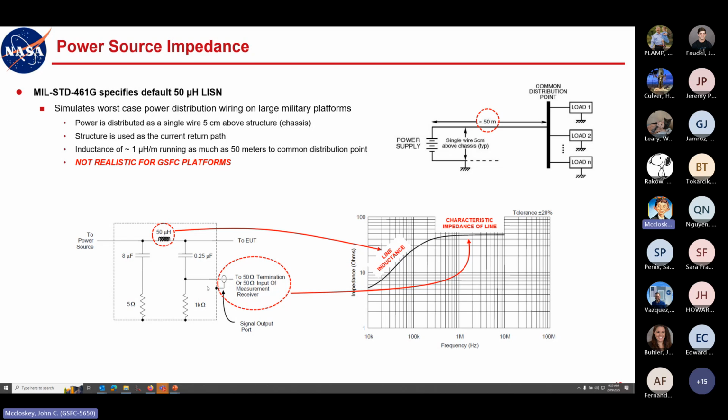And you just do your Thevenin equivalent analysis, right? The source impedance that your device under test will see looking back in this direction, per Thevenin. I should probably add a chart on this, but you short out your power source, and at high enough frequencies you're shorting out this capacitor, so it doesn't really matter.